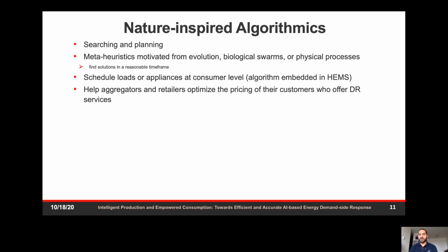So home energy management systems, or HEMS for short, aggregate the different appliances that you have in your house, and they monitor the energy usage levels that come out of these different classes of appliances or individual appliances, and they can control turning them on and off. So these home energy management systems provide a high level of granularity in terms of energy usage data, whereas a smart meter doesn't necessarily provide this level.